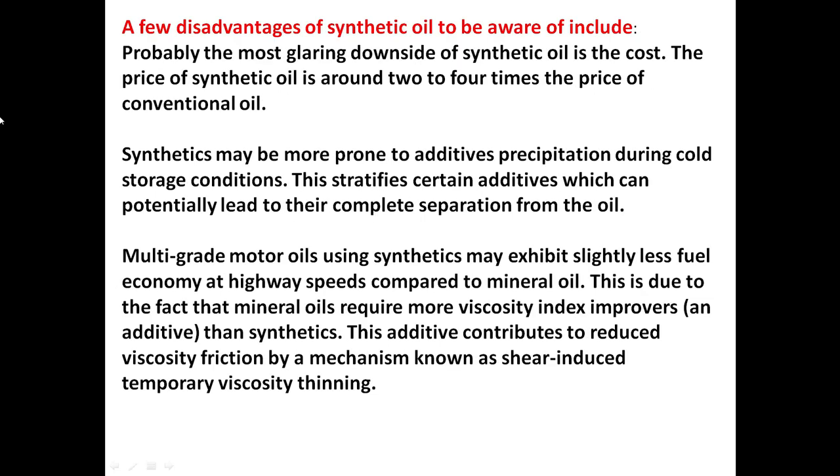The few disadvantages of synthetic oil to be aware of: probably the most glaring downside of synthetic oil is the cost. The price of synthetic oil is around two to four times the price of conventional. Synthetics may be more prone to additive precipitation during cold storage conditions. This stratifies certain additives, which can potentially lead to their complete separation from the oil.